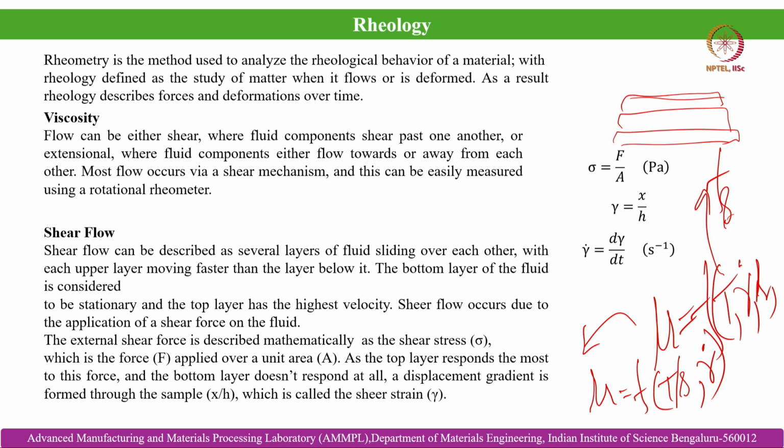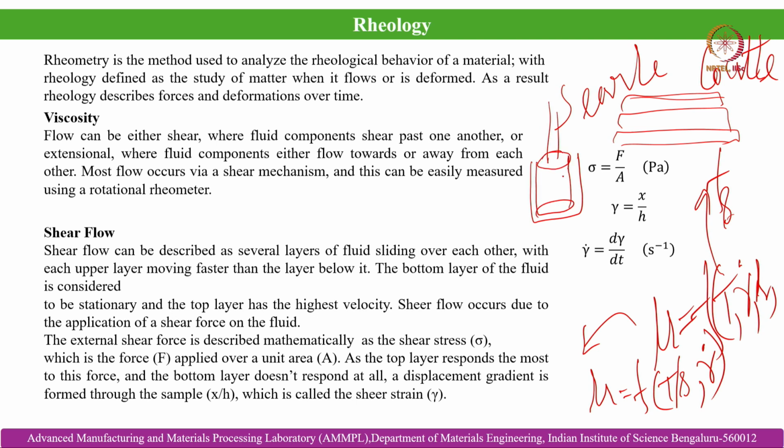So, how can we measure the rheological attributes of the solidifying melt? That is by using a rotational rheometer. Rheometers can be of different types. Based on the measuring geometries, we can differentiate rheometers as Searle type and Couette type. What are the primary differences? Assume that this is your measuring geometry. You can name this the rotating bob, and this is the stationary cup.